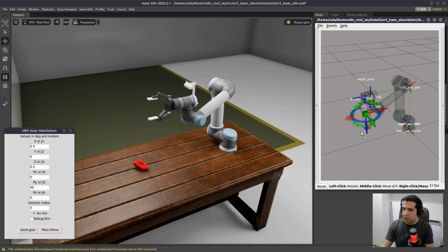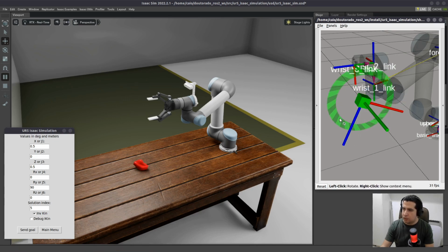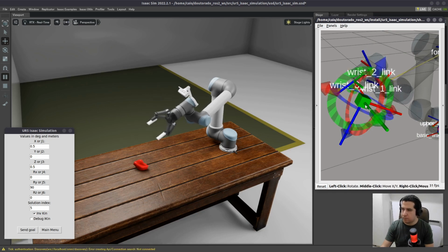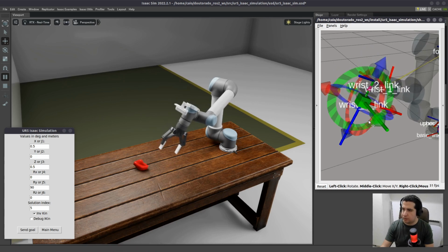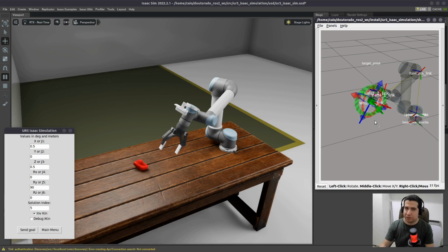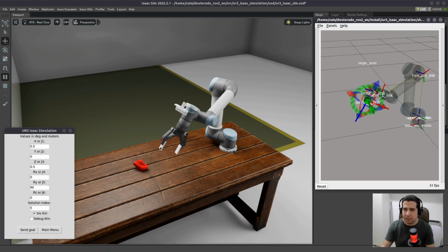So be aware, pay attention to this detail here. The end effector is pointing to the z direction of the marker. So if we put the marker in this orientation, the robot will move and reach the position that you configured. So be careful to not set, I don't know, a crazy orientation and you get an error or maybe hit the table. Yeah, let's go to the presentation.